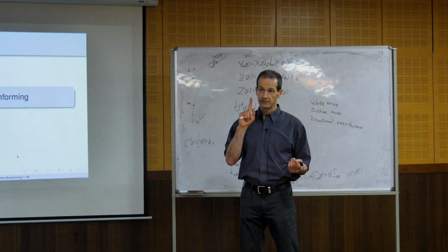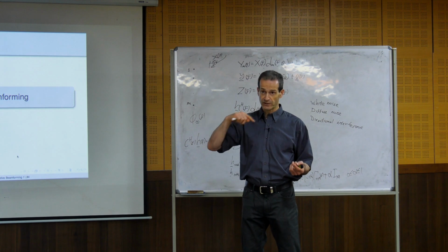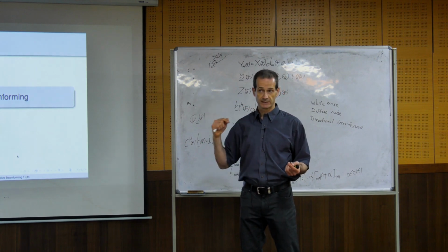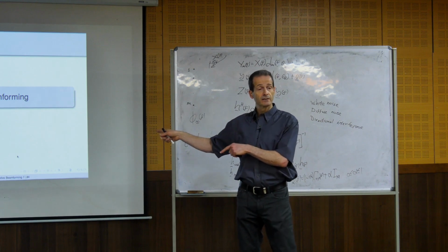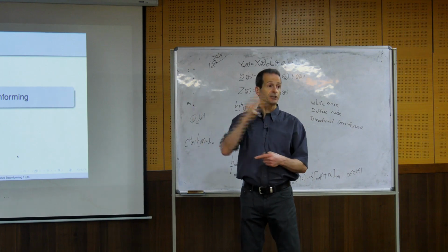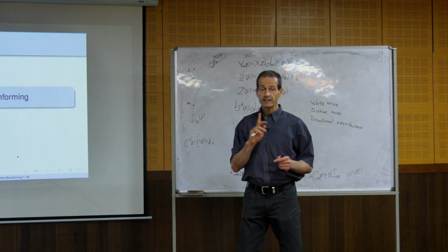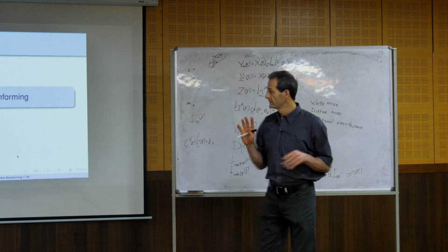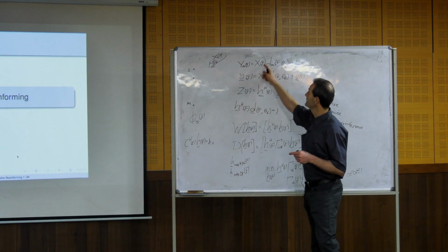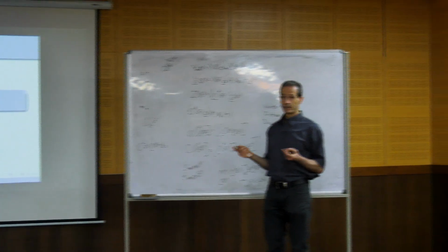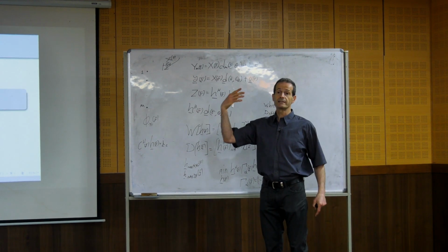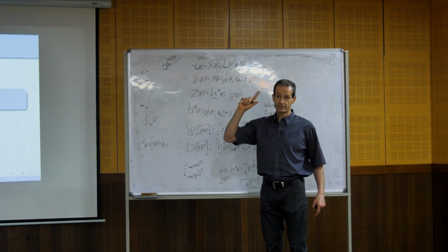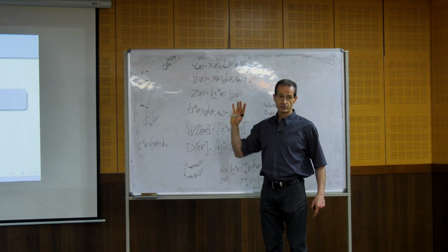Also in the LCMV, we put constraints on relative transfer functions related to interferences. With LCMV for adaptive beamforming, we put constraints on directions. You see? So the only difference is the definition of the steering vector. Is it actual direction in free field, or is it derived from relative transfer functions? This is the only difference.